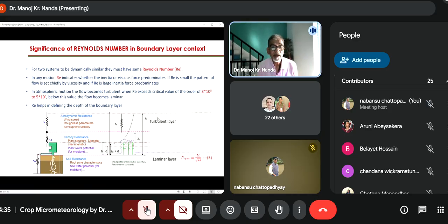And this is my turbulent layer here. And the turbulent layer depth is 0.37 L by fifth root of Reynolds number. So these are the two threshold limits of turbulent depth and laminar depth. Now you understand how much should be the depth. Now within this depth we'll consider.